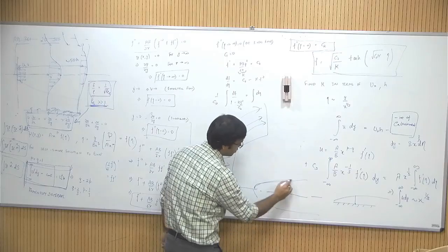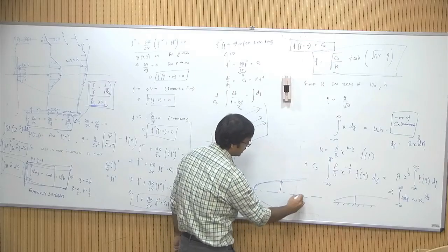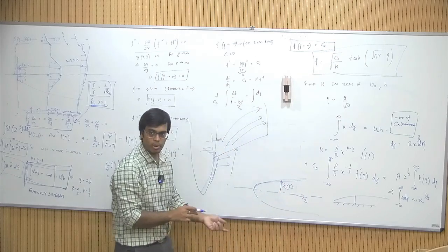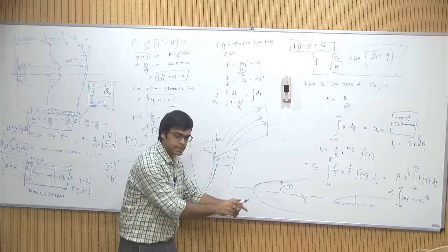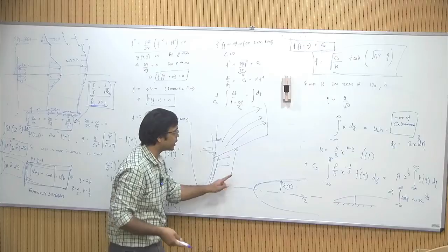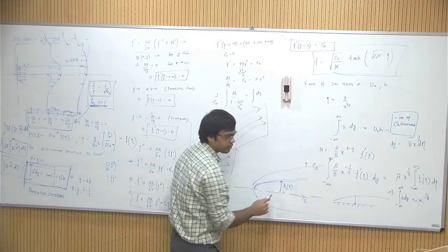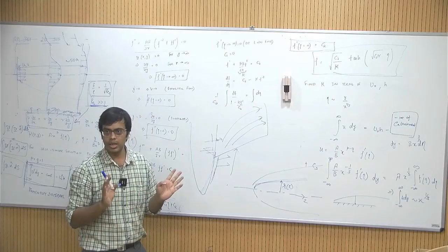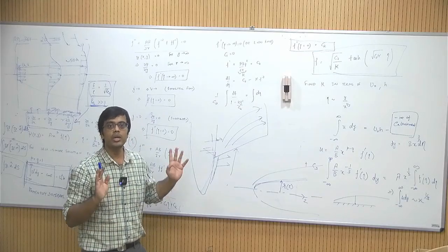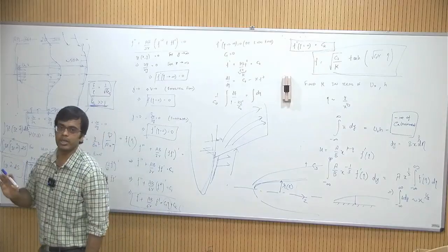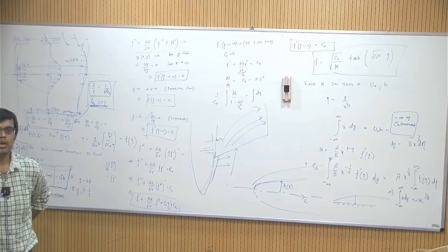Okay. In axisymmetric flows what you have is, let us say this as z, you have r that is a function of z. Okay. This is the body of revolution. So, this is the axis and you have revolved something like a cone, you can imagine a torpedo or a missile or something, and then you have a boundary layer on top of this. Here also you can formulate the self similar equations, a self similar solution. You cannot solve it analytically, but you can at least get something of an equivalent of the Blasius boundary layers.